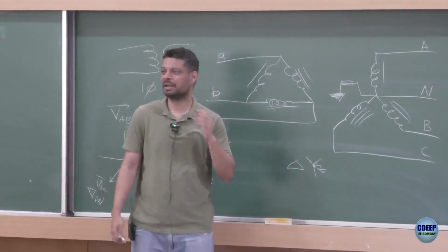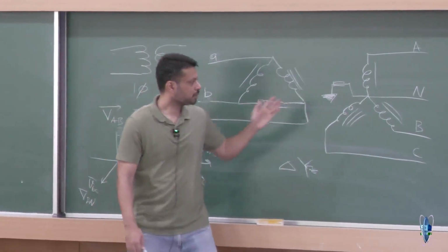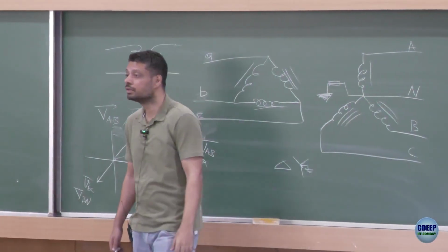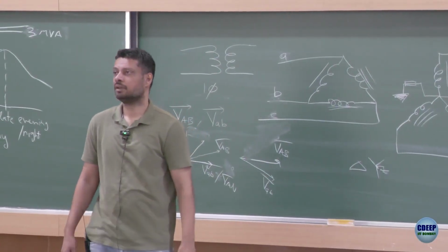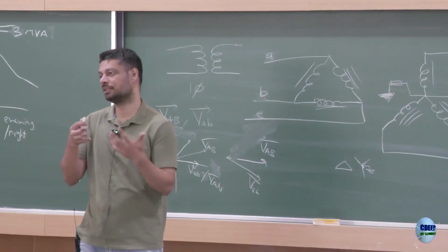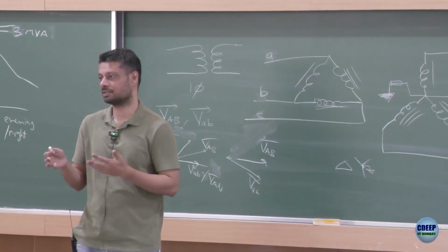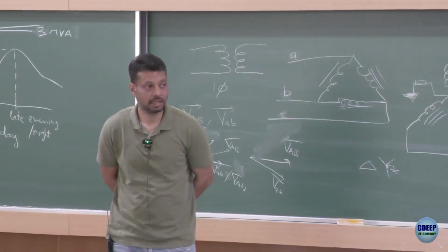You won't do that. Now, why would you do that? Yeah, you would connect a load on this side, no? Oh, higher power, you mean? So if you are paralleling, if one is a star delta, the other one also has to be a star delta, or if one is a delta star, the other one also has to be a delta star. Yes, the load is connected on the star part, star star, okay.